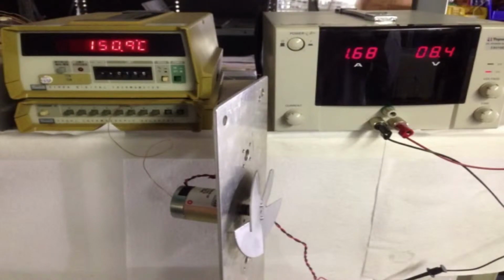Since the motor is now stabilized at a lower temperature, I can increase the load. This will cause the temperature to rise again. Once the winding temperature has stabilized around 150 degrees C, I can see that this motor is now able to draw 52.7% more power and produce 13.5% more torque based on current.